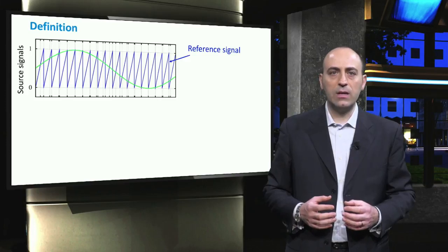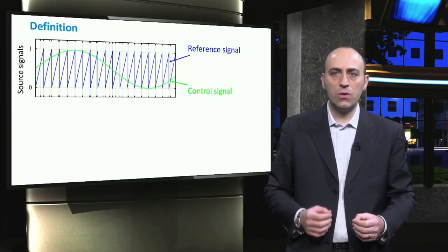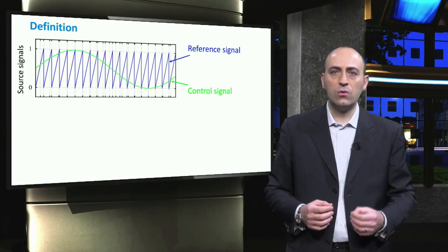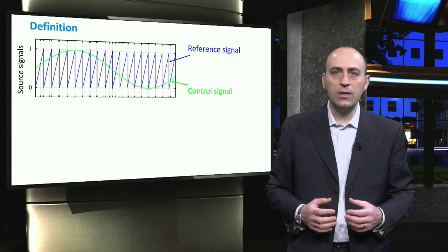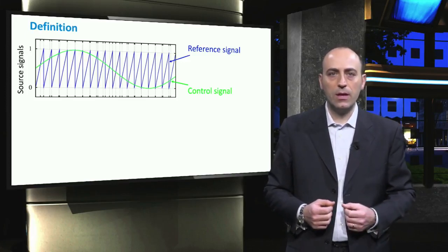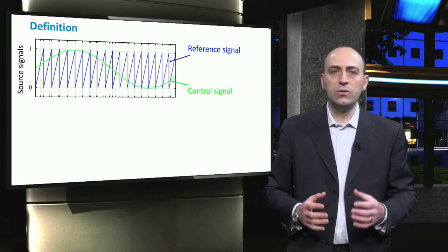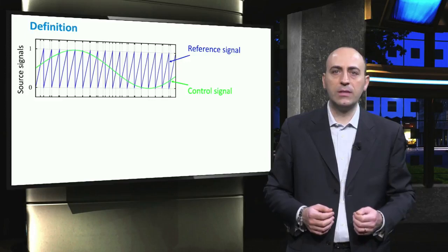The second signal is called the control signal, and it is a pure sinusoidal wave that allows to control the frequency and amplitude of the H-bridge output. Usually, this sinusoid is directly retrieved from the main grid signal. As mentioned before, these two signals are compared in a time frame to obtain a PWM signal that is used